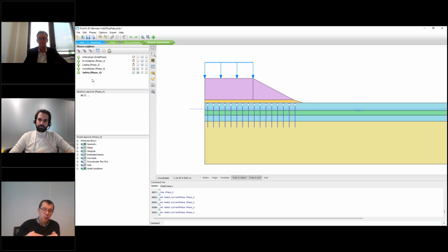You take that horizontal effective stress applying onto the rigid inclusion, and then just use a simple Coulomb friction law, c plus sigma times tan phi, times a certain coefficient, 2/3 or a bit less depending on the situation. Then integrate that shear stress, which is fundamentally the Qs that one can mobilize along the rigid inclusion, times the perimeter. You should also get a very good order of magnitude.